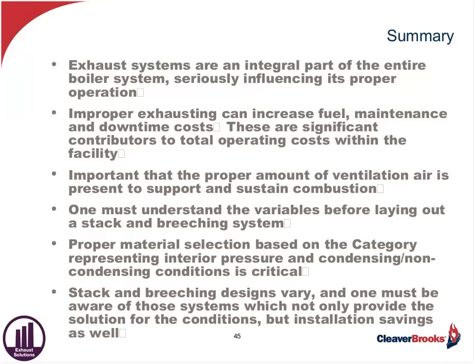Now, if it's cold temperatures, and you've got this open area, let's say it's louvered, you can have dampers put on there that are tied into the control circuit of the boiler or boilers, and would only power open under those conditions when the boilers are firing, and then would drive shut when the boilers are down. Of course, when the boilers are firing, it's going to warm up that boiler room considerably.